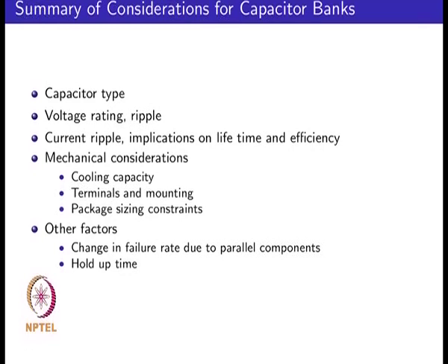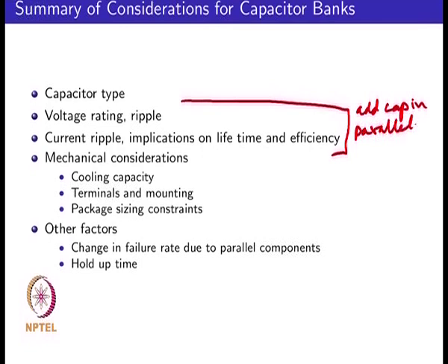The current ripple has implications on life and efficiency. If you are tight on these two factors, one might consider more capacitors in parallel. However, you also have mechanical considerations. From the cooling perspective also, if you put more capacitors in parallel, you have more surface area for your capacitor bank.